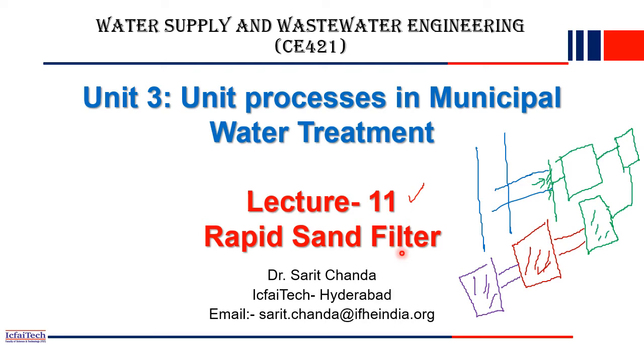In the slow sand filter, filtration takes a longer time because the dimension of the sand particles is very small. That's why water takes more time to travel through the filter medium, and less quantity of water is filtered out. Whereas in the rapid sand filter, the dimension of the sand particles is a little larger, so the pores are also larger and the filtering capacity is increased. That's why in the municipal water treatment plant we use the rapid sand filter, because the water demand is very high in the municipality.